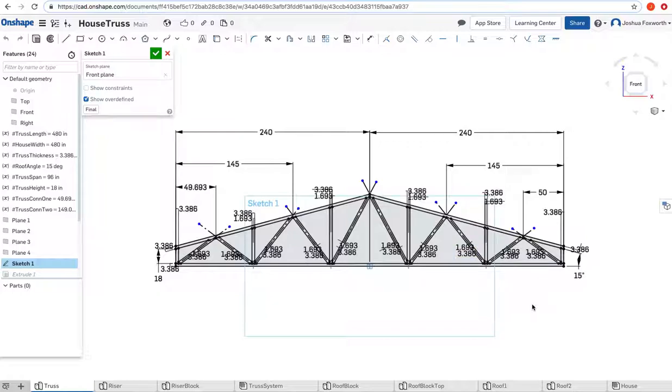So a couple of examples of that are that it's tempting when you draw a truss like this to define everything either from the center out or from a side into the other side, or maybe from the bottom up. But those aren't the parameters that are driving the design of this truss. The actual parameters are the thickness of each member. That's what's important to us, because we want those members to be able to hold the stress, and then where these connection points are made.